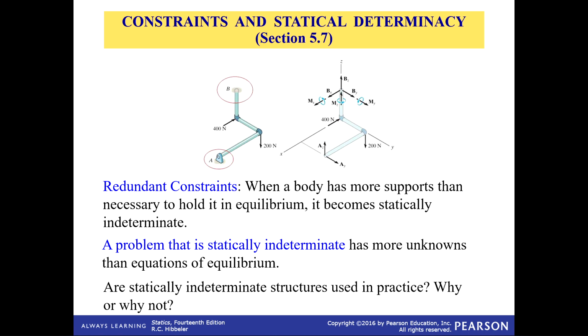Could this be used in practice? Yeah, it might be used in practice in real life because there might be forces that don't always act on the system that have to be considered. For instance, up north, there are these collar ties on the trusses in the ceiling of the house. Their only job is for snow and ice loads. So during the fall, the spring, the summer, when there's no snow or no ice, they do nothing. But during the winter, if you get a really heavy snowstorm and there's snow and there's ice, those extra supports provide the support to keep the roof from collapsing because of that extra weight.